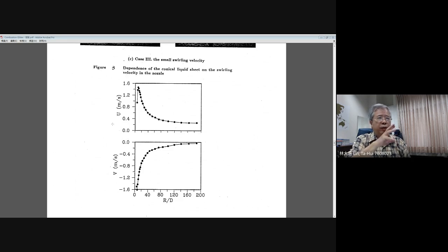But for the droplet, for water, since water is a very good seeding particle, right? But the size of the water droplet depends on the spray characteristics. Near the tip of your nozzle, you will have a large droplet size for the water, but downstream, maybe the droplet size will become smaller and smaller. But anyway, in the process of atomization, the water droplet itself can play as the seeding particle. Then you can have some data coming from the motion of your water droplet.